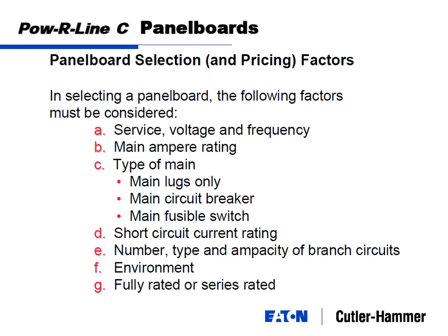So when this presentation gets posted, this is one of the pages that I would suggest when you're doing your designs. This is what a manufacturer is going to look for in a panel board. When you say, give me a panel board, how much? I'm going to say, well, what's your voltage? What's your frequency? What's your main amp rating? What kind of main do you want? Main lugs, main breaker, main fusible switch? What's your short circuit current rating?